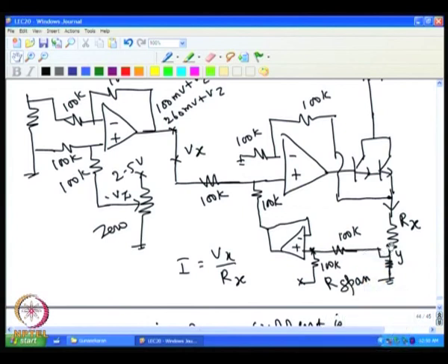Now, to make it 4-20 milliampere, keeping this 100 and 260 millivolt variation to 4-20 milliampere is not an easy solution, because the ratios will not match. One has to do a lot of jugglery in terms of resistance variations. Or, as another possibility, we can also add the voltage at the plus input. So, one can add the voltage at the plus input, like instead of adding it here, I remove this.